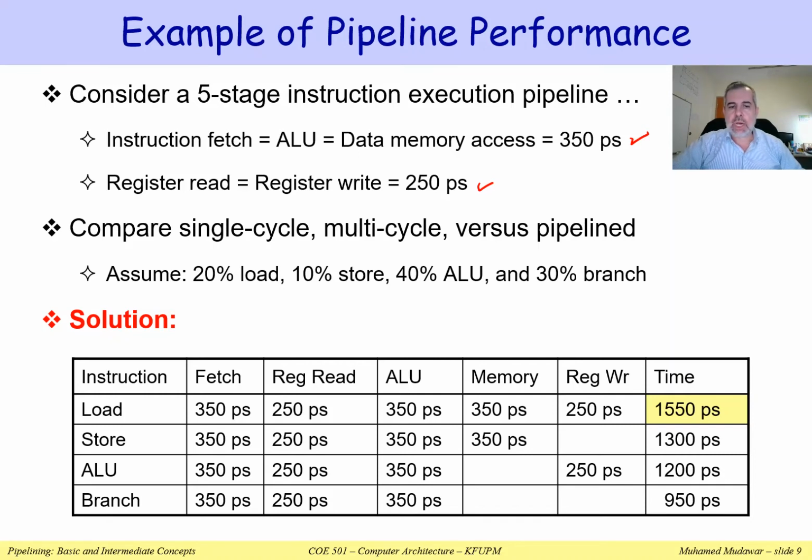And at the same time, we are reading from the register file. It takes 350 picoseconds to execute on the ALU. That's the delay inside the ALU. I'm assuming simple ALU instructions, so there is nothing complex. For example, I'm not talking about a divide instruction that takes longer to execute. So simple ALU instructions like simple arithmetic, addition, subtraction, or logic operations. These can be done very quickly inside the ALU, and the delay is really short, which is given here as 350 picoseconds.